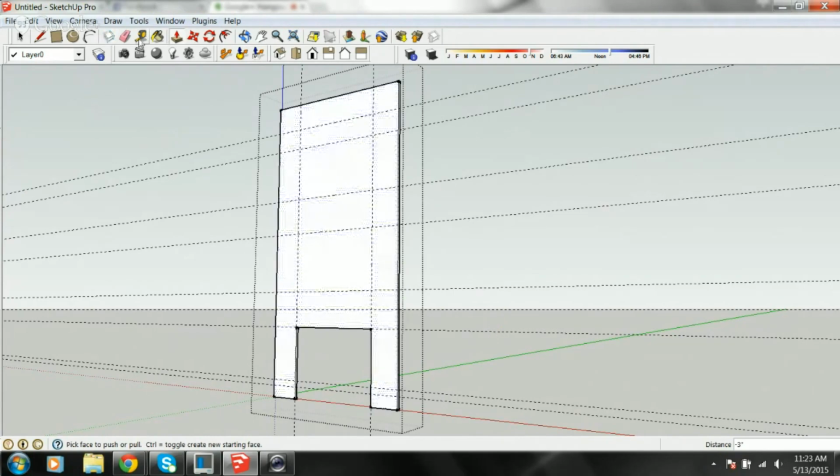Okay, so now you'll see in the image, if I just go up to the windows, it looks like I've got what I'll say is an 8 to 12-inch band around that second floor set of windows that's an accent in the brick. And it's inset from the right side on each side here. I just kind of like to draw a line straight up and down. So I'm going to come here, grab that. I'm just going to say 8 from each side.